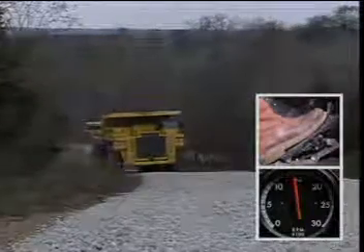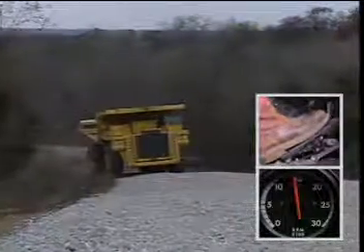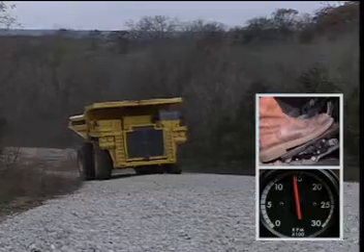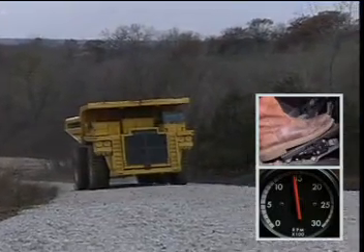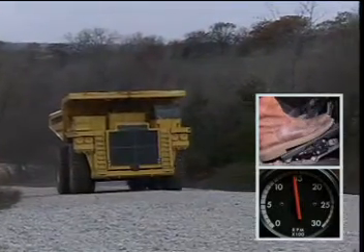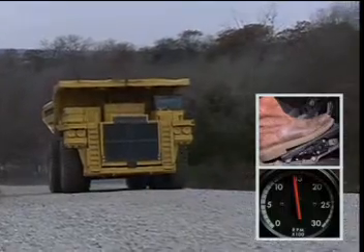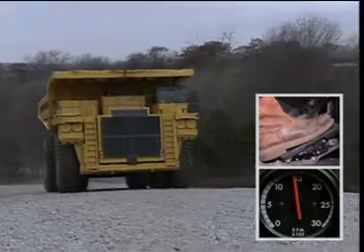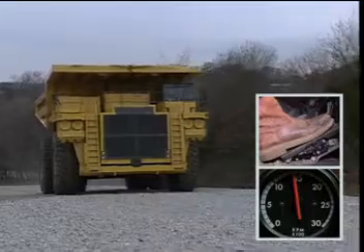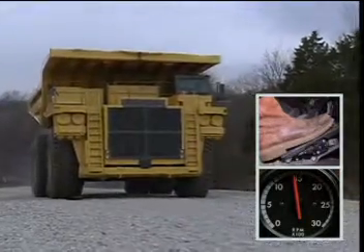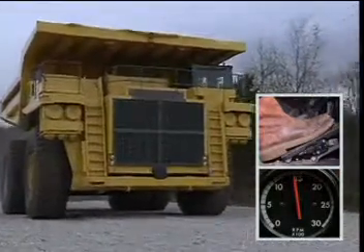In some applications, it is desirable to provide the ability to continue equipment operation after an accelerator failure occurs. The accelerator limp home feature provides this capability. Accelerator failures are any out-of-range accelerator conditions. Idle validation is required to use the accelerator limp home feature.